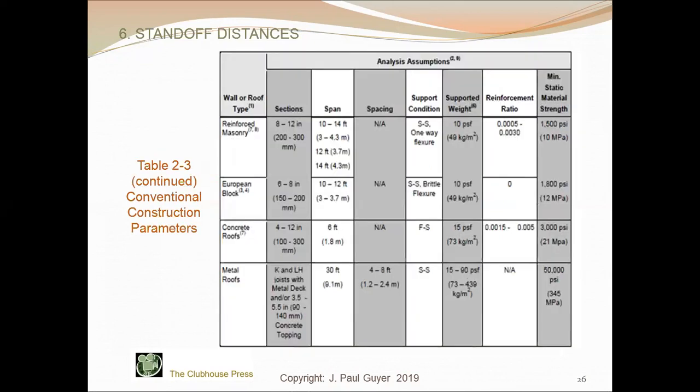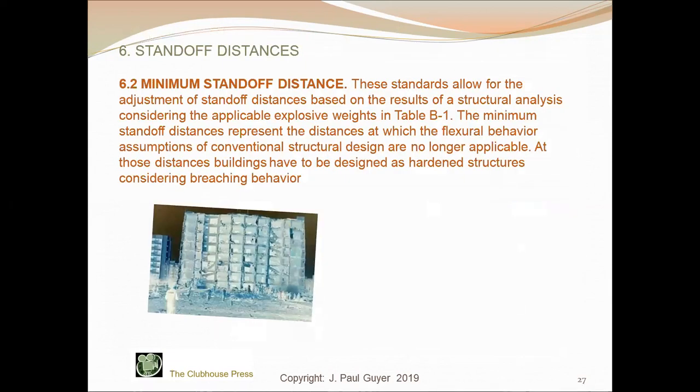So continuing on, this slide 26 is just an extension of table 2.3. Now, minimum standoff distances. These standards that we're talking about today allow for the adjustment of standoff distances based on the results of a structural analysis, considering the applicable explosive weights in table B1.